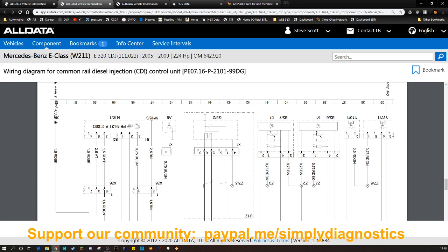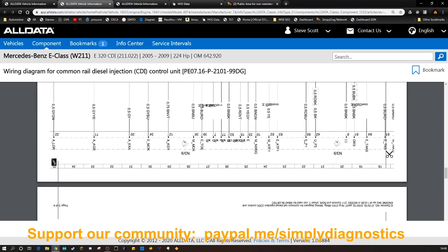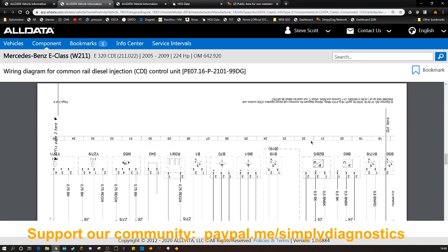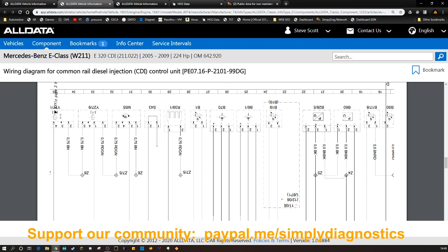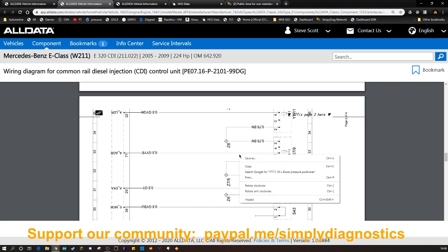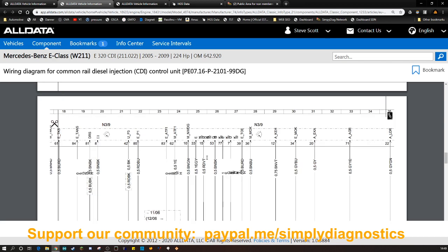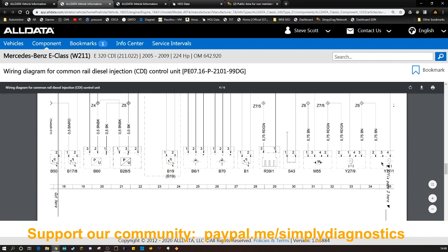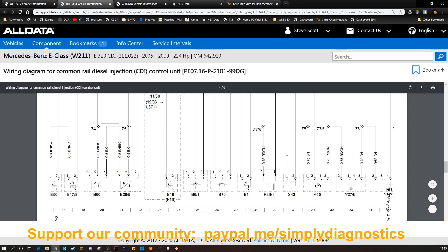Okay, so what's that showing me? 1543. So it's right on the join. So what we can do is rotate clockwise again. It's a bit of faffing about. But there's our Y77.1. So we can see straight away we've got a brown there and a brown on the next component over with a Z connector, right? That's a Z connect. There's a connection there. We can find that afterwards.